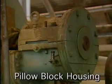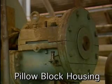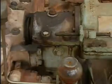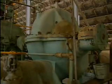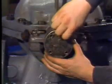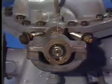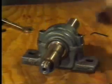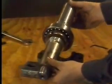Pillow block housings are located outside the machine casing and are separate from it. In some cases, the pillow block housing holds the end of the shaft. In others, the shaft passes through the housing. Pillow block housings can be either solid or split, and they come apart in different ways. Some solid pillow block housings have a removable cover. Once the cover is removed, the housing can be moved out of the way and the bearing can be taken off the shaft. With a split pillow block housing, the top of the housing can be taken off. The shaft can then be lifted out so that the bearing can be removed.